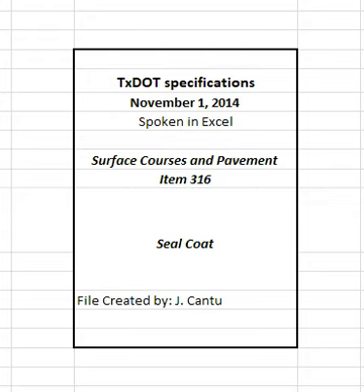4.4.3 Asphalt rubber temperature limitations. Do not place hot asphalt rubber seal coat when, in the engineer's opinion, general weather conditions are unsuitable. Apply seal coat when the air temperature is 80 degrees Fahrenheit and above, or above 70 degrees Fahrenheit and rising. In all cases, do not apply seal coat when surface temperature is below 70 degrees Fahrenheit.